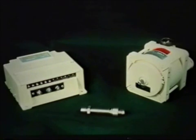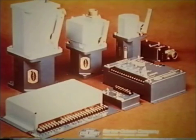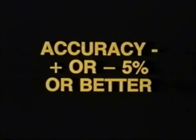Frequency regulation, unlike voltage regulation, cannot be controlled by an alternator or its accessory equipment. Regulation of frequency is purely a function of the alternator's prime mover and its speed governing system. Governors are available in a wide variety of devices, from simple flyball types to very sophisticated electronically controlled systems. The degree of accuracy can range from a regulation of plus or minus 5% to plus or minus 0.5% or better.